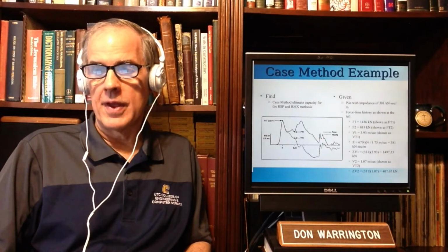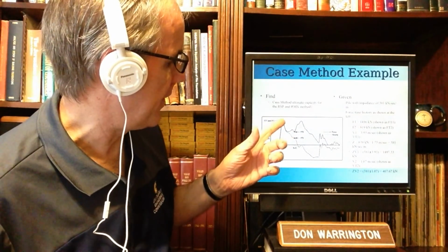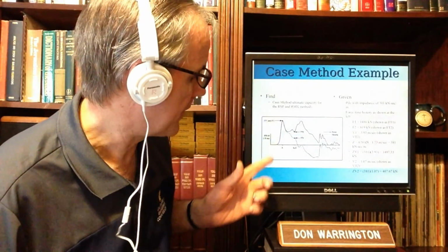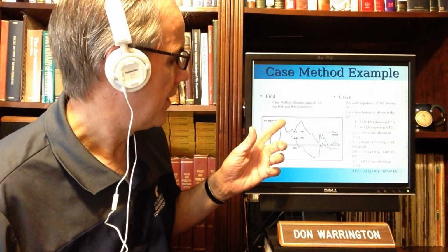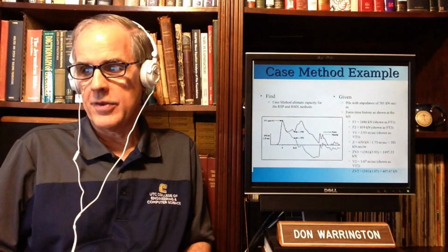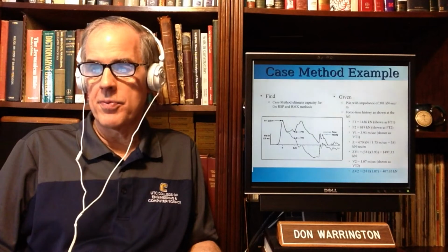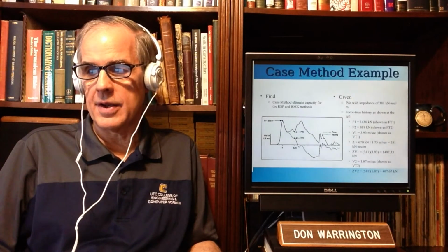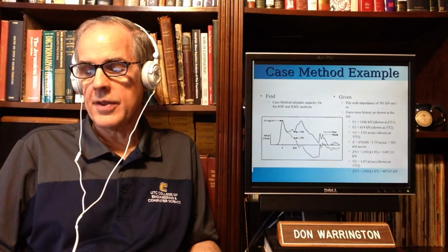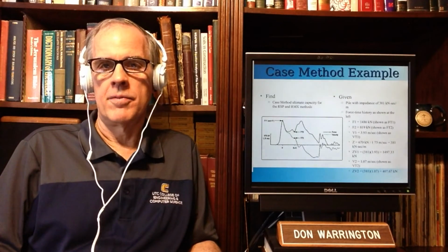So what do I do? I start with this. I scale this up. I will try to give you a better scale, just as a disclaimer. I'll try to give you a better scale on this side. F1 is 1406 kilonewtons. F2 is 8. You're reading it right off the graph at the two different times. V1, 3.93 meters per second, and ZV1, the impedance, is 381 kilonewton seconds per meter.